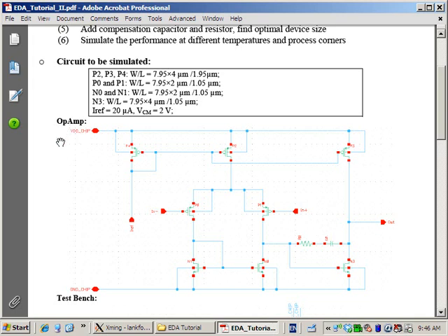If you have a very long transistor, like 32 micrometer, and the length is only 2 micrometer, it looks weird. It's gonna be very long, something like this, right? And that is not good. So we have to break down using multipliers in our process. For the details of how to use multipliers, we will cover it in layout. So for now, we just need to know that 8 times 4 means the total width is 32.